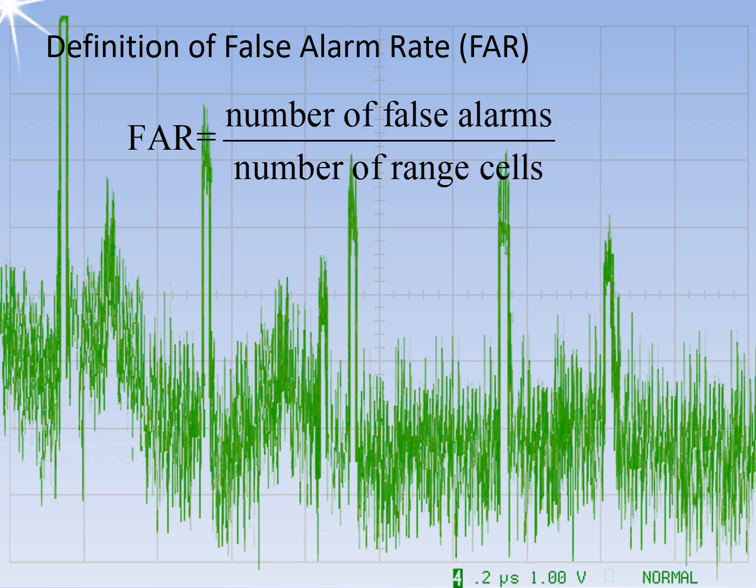The maximum number of potential target acquisitions also determines the maximum number of false targets. This concerns the theoretical case in which there is a target signal in each range resolution cell. In digital radar, this is the number of range resolution cells. In classic analog radar, the maximum possible targets are determined by the ratio of receiving time to transmitted pulse duration. Alternatively, the ratio of maximum range to range resolution cell size could be used.